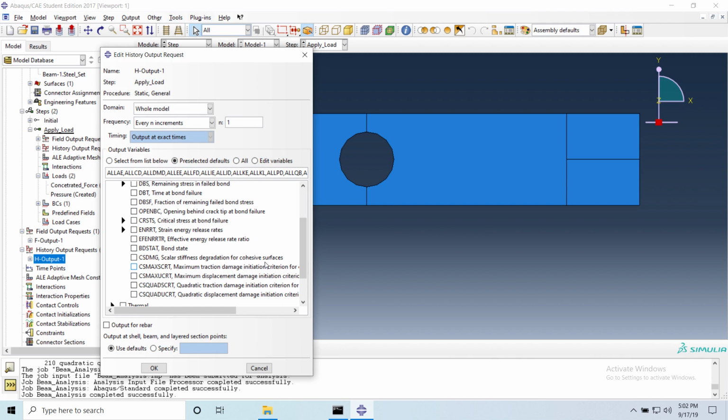No, only for the last step, because this is a linear increment. So you don't have the visualization for the middle of it. Even if you apply the entire load, because if I want something in between, then I have to split my linear increment into 2 linear increments. So I'm only solving the system of equations once. So you define your step for only one. Correct. It's only one increment.